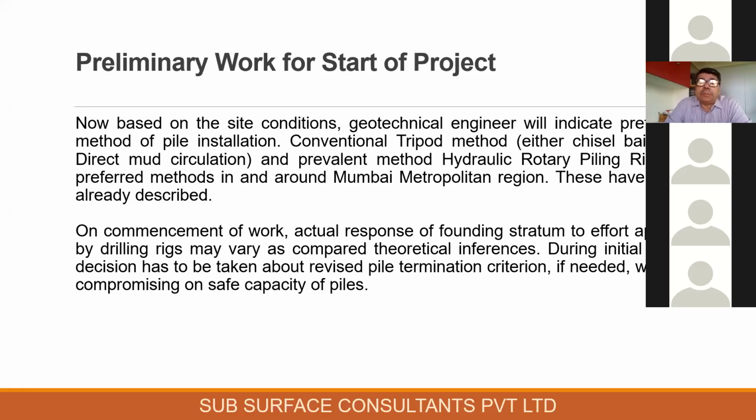Typically in the Mumbai region, the MMR region, the conventional tripod method using chisel and baler or direct mud circulation is carried out, or the more prevalent method today, after 1995, is the hydraulic rotary piling rig. These two methods are preferred in and around Mumbai, and have been adequately described by Mr. Jain Kulkarni before me, so I wouldn't go there.